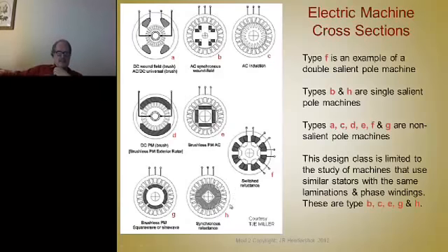Now here's an extreme example of a reluctance machine that has poles that look like a gear on the rotor and poles that look like a gear on the stator. If you look at this winding here, the flux is going to go through there like that. There's very little air gap in the circuit. It's all iron, with a very tiny clearance gap. But in this set of poles, there's lots of air gap in the circuit, this great big air gap. So the inductance here is very low, and the inductance there is very high. There again, we're in quadrature here.